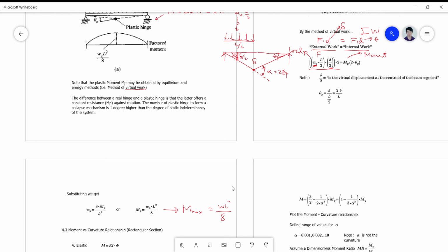So that's the moral lesson there. Do not do a plastic design on a simply supported beam. Aside from it being dangerous, it simply gives you the same degree or level of magnitude when it comes to the comparison between the plastic moment and the maximum moment.